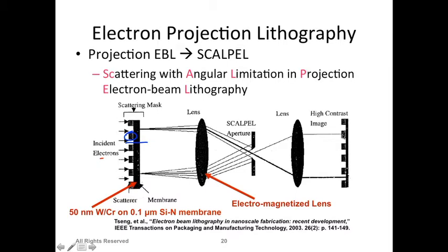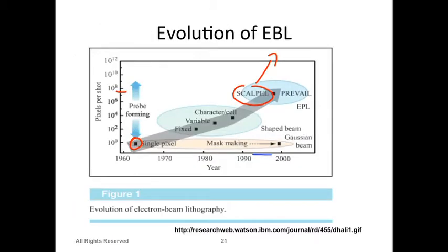So then you have to choose a photoresist which should be sensitive to this kind of electron energy, not the other. It means it should require enough energy before it can resolve a pattern. So by doing it, you can use a mask. With this technique, you can actually improve the throughput of a system. I don't remember off the top of my head what the resolution was, but I believe it should be lesser than the regular e-beam lithography. Okay, I think I have a graph here. Let's look at the graph.